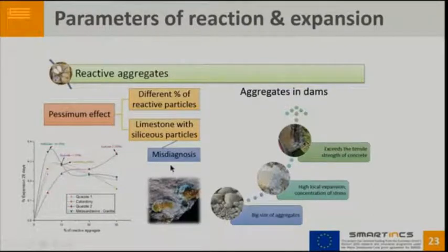And in this case, we can have the pessimum effect, that is, with a small quantity of reactive siliceous aggregate, we have the same behavior as other aggregates that need some more quantity to have the same expansion.